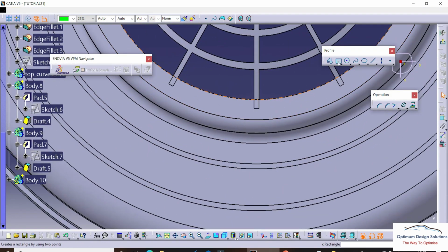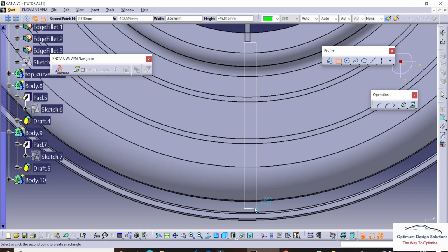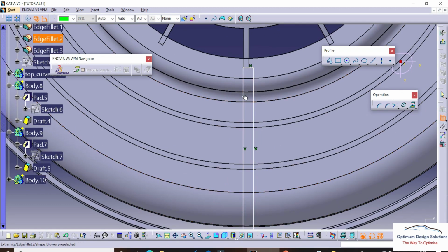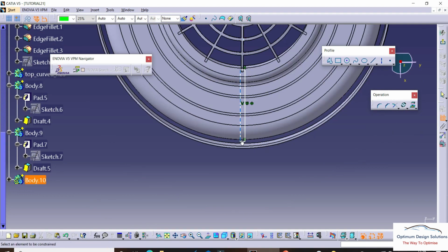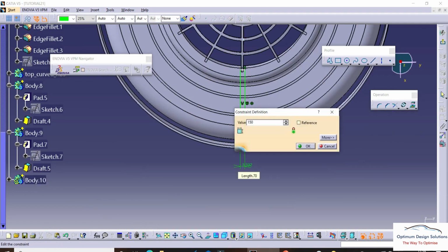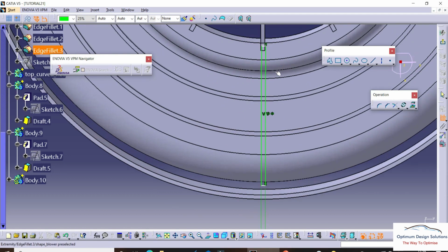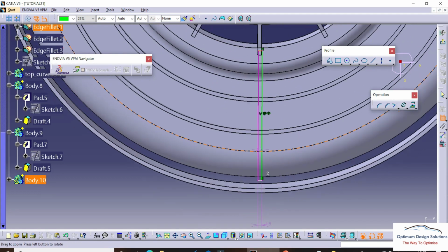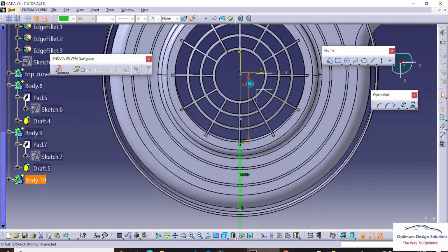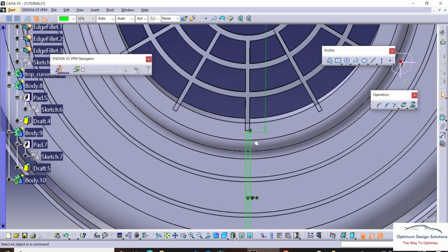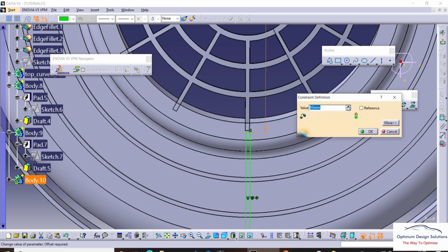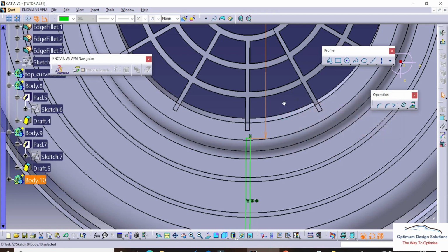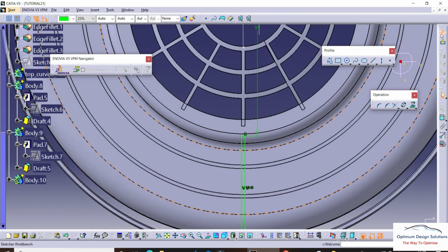So here the supportive central rib we are going to design. The dimensions and everything are similar to what we drew for the top side ribs. The thickness is 1.2 mm and the length is as per our requirement.